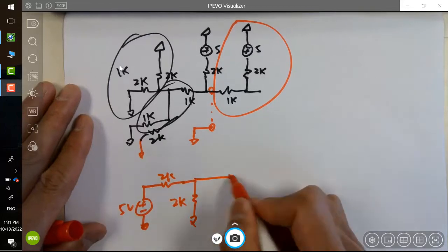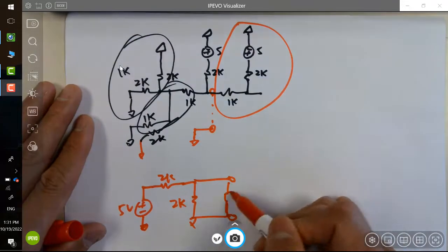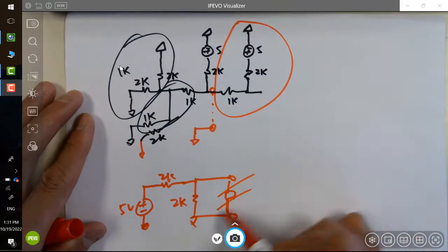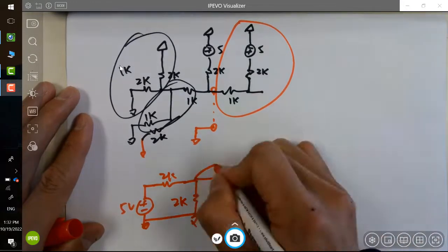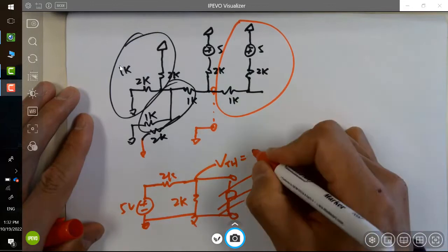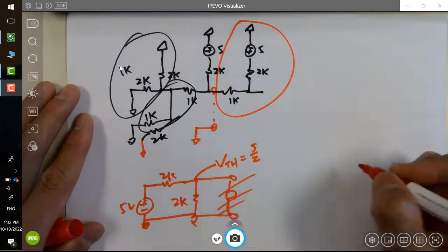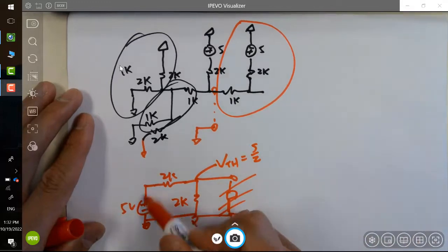Okay. And here's a network. That's a load. Whatever load there is, it's just a box. So you want to remove that one first. And that's a circuit. So what's ETH or VTH? What is RTH? You remove the load and look backwards and short it, right?